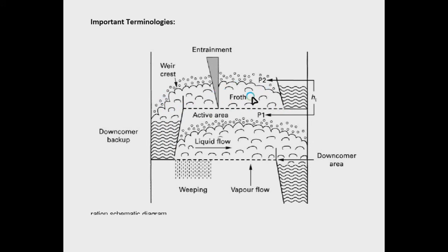And in certain cases the liquid holdup is far greater, but the vapor flow and pressure are analogous in this column, because a higher flow of vapor will increase the vapor pressure here. If we have a high pressure, the liquid will not weep or cry through the plate, because the pressure will be high enough. But weeping can take place and it is discouraged. The weeping should be minimal in amount. And also a froth can be formed.